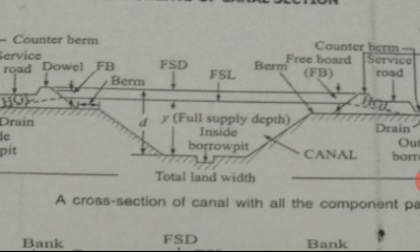If side slope is more than angle of repose during construction, after the bank has been exposed to weather, eventually it maintains the angle of repose. Height of canal bank decreases, the width at bottom increases.